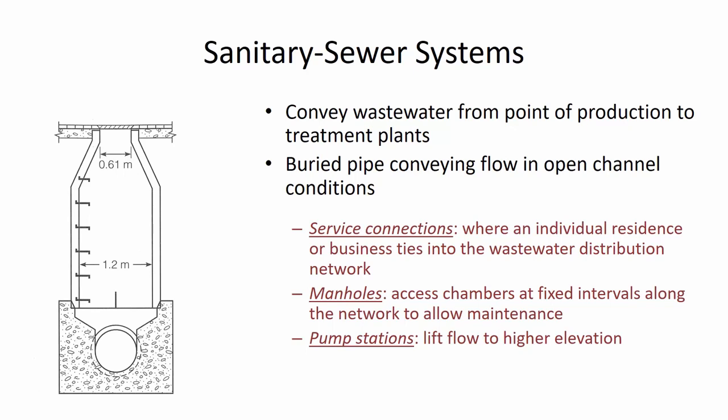They do that intentionally so that when tree roots or whatever else may cause problems with your lateral connections, whenever there's an issue, that's your responsibility to have someone come out and fix it. Those are the most vulnerable pipes, the ones that have the smallest diameters, that are at the shallowest slopes, and that are closest to vegetation, because they can become clogged and broken pretty easily.